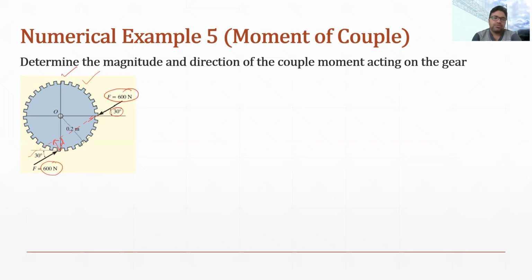Now you can see finding the distance d will be a little difficult in this case. So what we can do is apply Varignon's theorem. According to Varignon's theorem, the magnitude of the moment will be equal to the algebraic sum of the moments of the components of these forces.